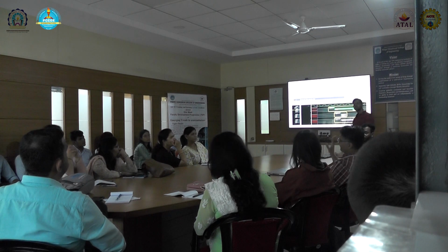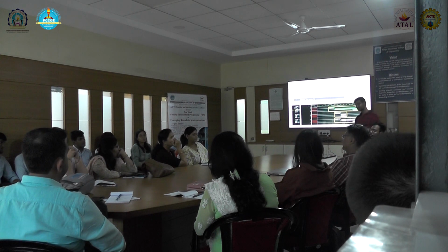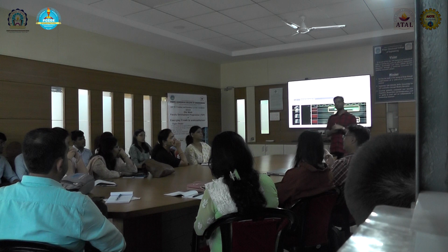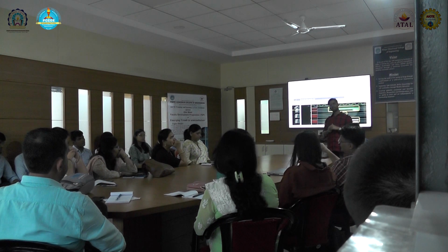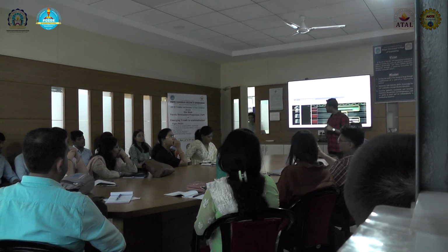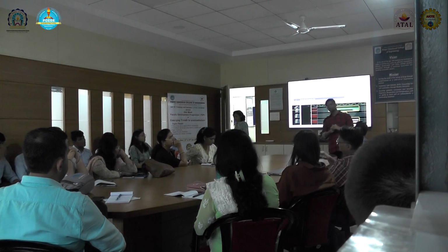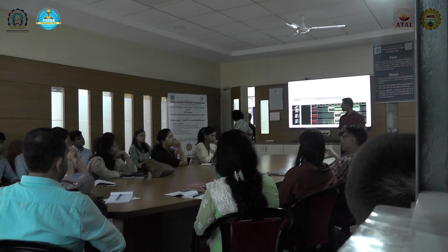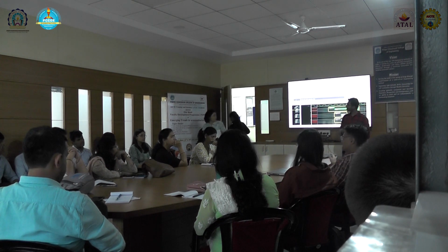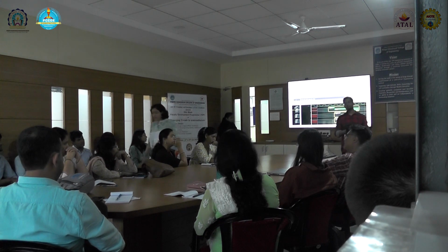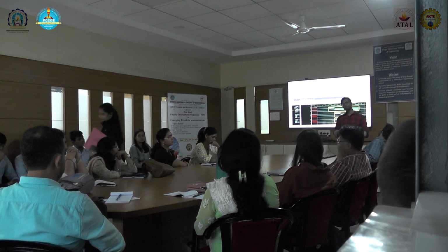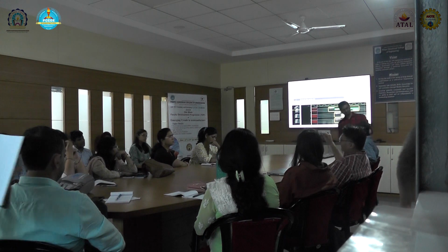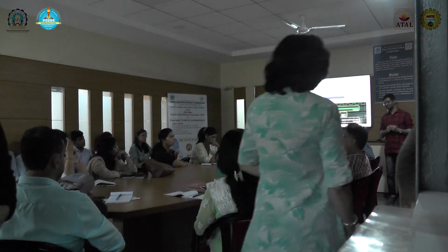Let us say you have a FIFO, and I'm just giving an example. So FIFO can be of two types. One where you expect that over a period of time this FIFO may get full. But there are also FIFOs where rates are matched. Input आया, output निकल गया. So in those FIFOs you never expect it to be full. So you can write an assertion that FIFO full should never occur.